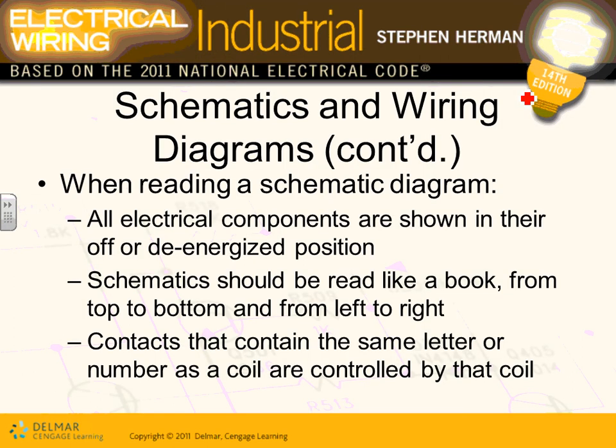So when you do schematic diagrams, I emphasize that you read them like reading English, not Arabic, right? You read from left to right. So schematics should be like reading a book. They should be read from top to bottom and from left to right.